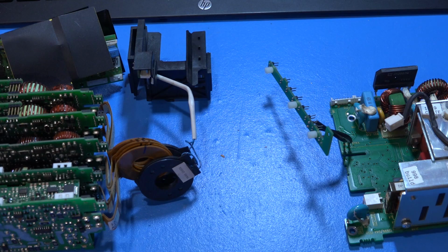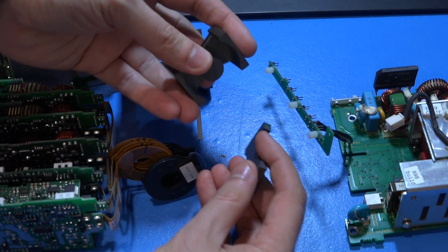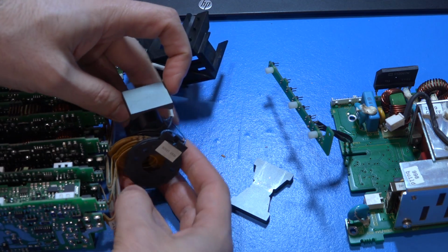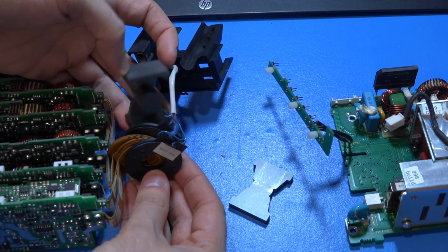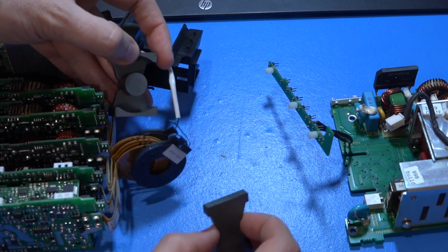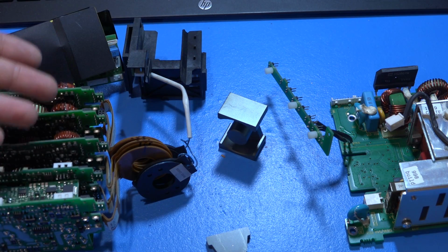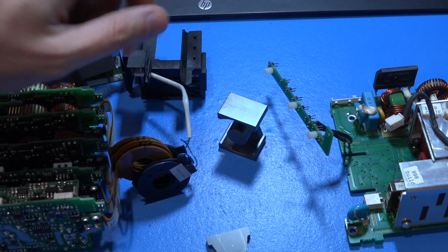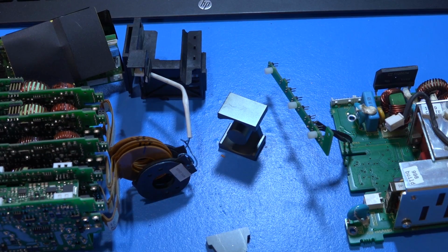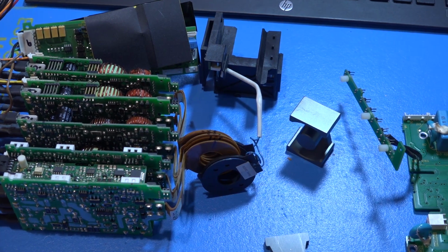And in order to maintain and confine that, they have a perfectly machined piece of ferromagnetic material which sits in the middle, and these guys just slide into this position here, and then this couples on the other side, clamps down, and there is your modular configurable transformer. So they make that on the fly. Depending on what modules you put, they just clamp it down together, and there it is, which is really quite incredible. So I really like this design. It means that you can basically buy any Vega 650 power supply and salvage parts out of it, which is what I think I'm going to do.